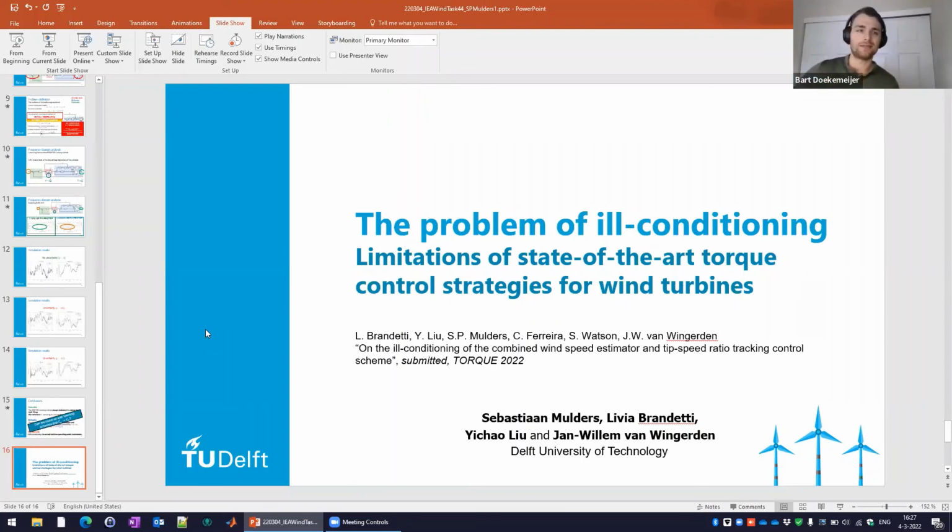Okay, interesting. Thank you. And then you said something about icing. Do you think using the temperature sensors in turbines in your algorithm could help with that? I think not really in terms of learning or in terms of correcting the CP table that is in our estimator or controller, but it might be beneficial for detection. So if you for example install microphones or temperature sensors, then you might be able to detect, okay, probably there's some kind of degradation, or some kind of effect going on in my blades, and now I need to do something about it. But for the active learning part, I do not think so.